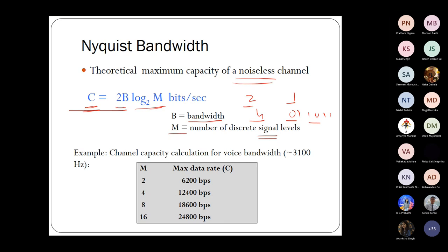When we do encoding, we'll see that these levels you cannot increase indefinitely. You cannot say 8 levels, 10 levels, and so on. Then you will need huge power, the gap between the levels will decrease too much, and your cost will increase like anything. So when we do encoding, we see what techniques people use. At least I will mention them, so you know the names. So this is what Nyquist says: take a channel, know its bandwidth, know the scheme you are using and how many signal levels. So 0 and 5 volt will be just 2 signal levels, and then compute this.